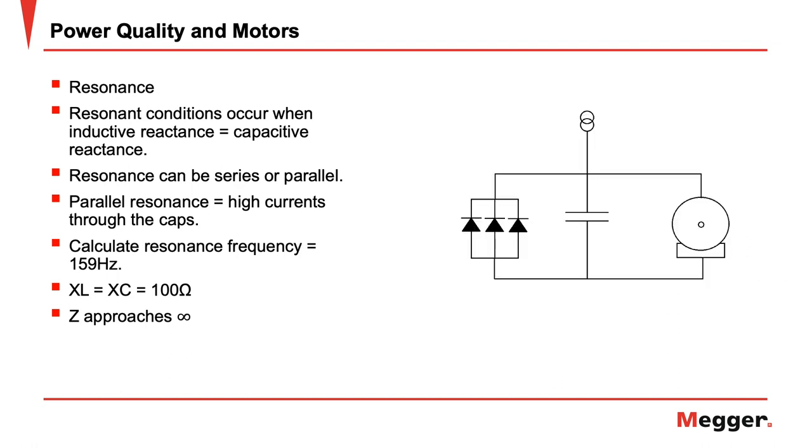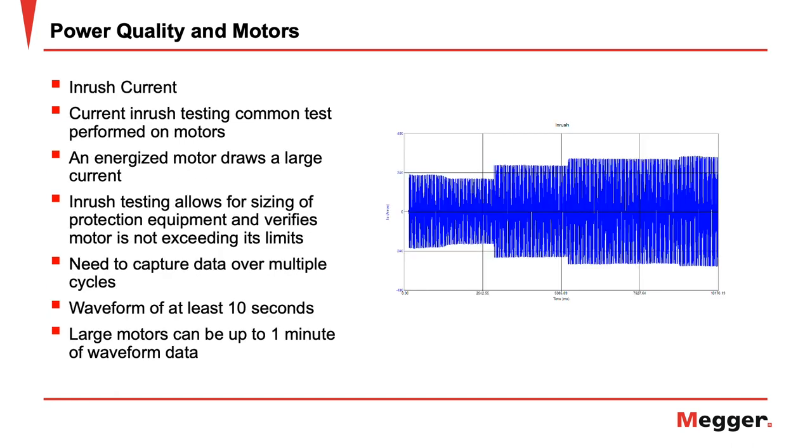The energy stored in the magnetic field in the inductor now collapses and runs through the cap, and the energy in the cap flows through the inductor, creating a high circulating current. At the resonant frequency, impedance is at a maximum, and high amounts of harmonic voltage appear because of the circulation of the harmonic currents. This results in major voltage distortion, as well as a high circulating current that can lead to catastrophic failures.